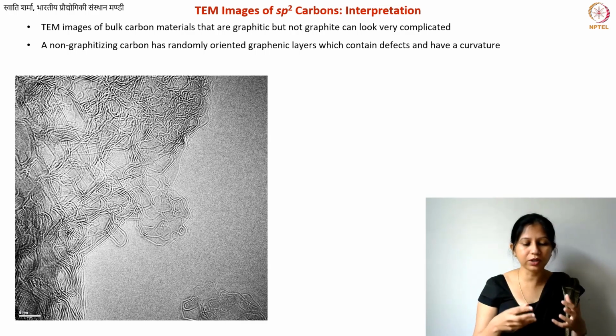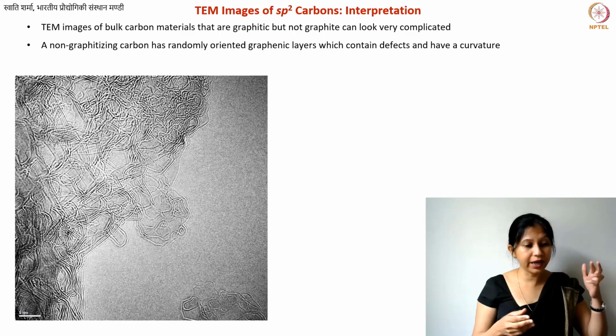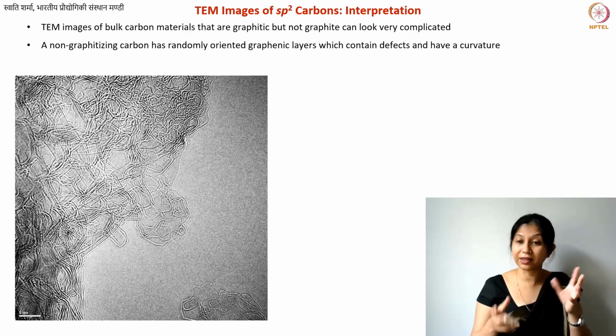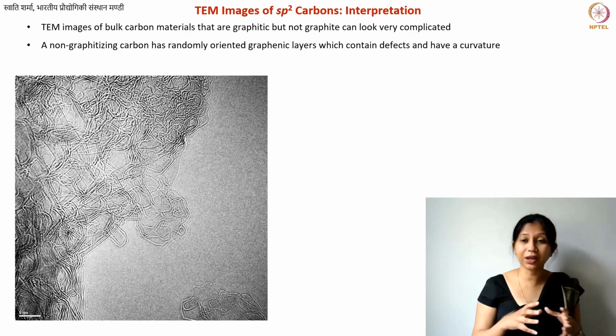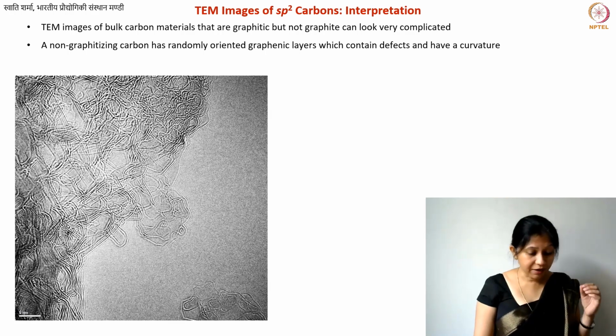So you will use this kind of grid, place your sample on top of it, and then perform the imaging. When you are performing the slicing using FIB, you may already place your sample on top of the grid inside the FIB system. This is how you analyze them. But you can also perform the heat treatment inside the transmission electron microscope, given your sample is extremely thin.